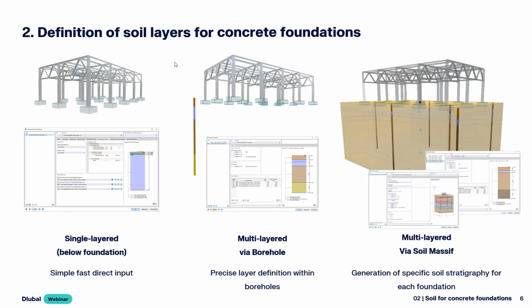We now have different methods for concrete foundations for the geotechnical design to define the soil layers. We have the type single layered, where you can directly in the dialog for the foundation define the soil layers, relatively simple and quick, a fast way of direct input of the soil situation.